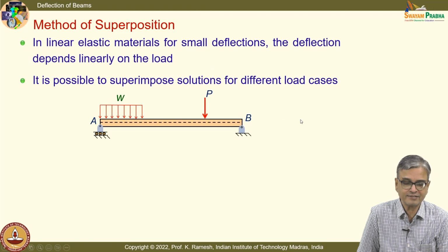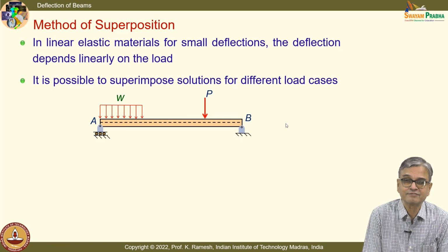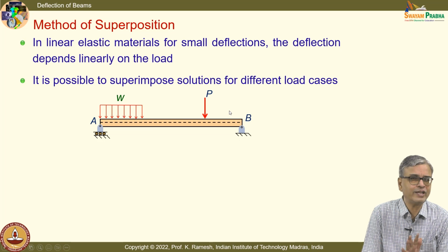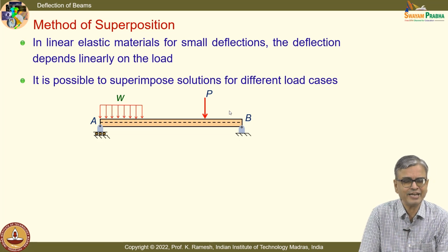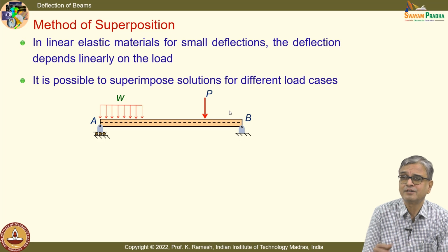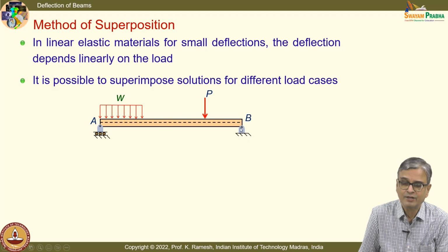Okay, I have a load case. Can you draw the anticipated deflection curve? Because I have the support, this is the roller support, this is the pin joint. I have unsymmetric loadings, the loading is not symmetric. Have a training, you make a mistake, no problem, you draw the deflected curve. So, you also learn how, because I can have any slope here, this also permits any slope, but the deflection is 0 at these 2 points, that is what I know.